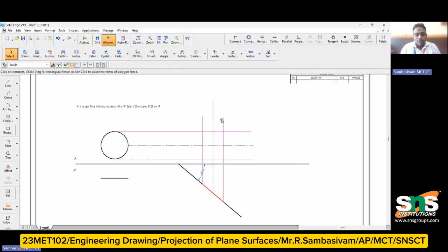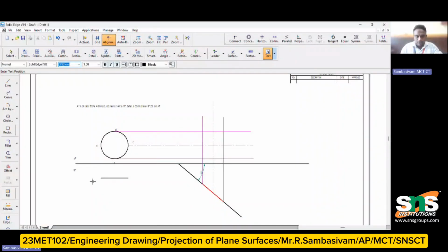So this is how the projection is done. Now I am going to mark this as A, this as B, this as C, this as D. So this one will be your A dash, and this point will be your B dash. In bracket, it will be D dash, and this one will be your C dash. Similarly, the line has been traced, right? This is your A dash. This is your B dash. In bracket, it will be your D dash. Then this one is your C dash. Then again, as I said earlier, the meeting point will be considered C1, and this point will be your D1, this point your A1, and this point your B1.